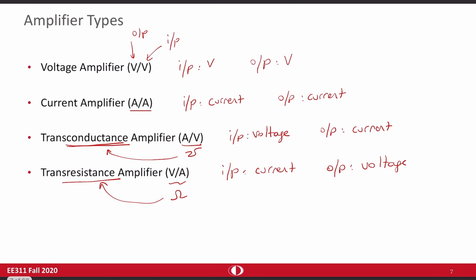Maybe I can write it in here. So AI is huge. I said we can use AI in dB. AV again huge. We can use AV in dB notation. And keep in mind that it's going to be 20 log A. For power, it's a bit different though.